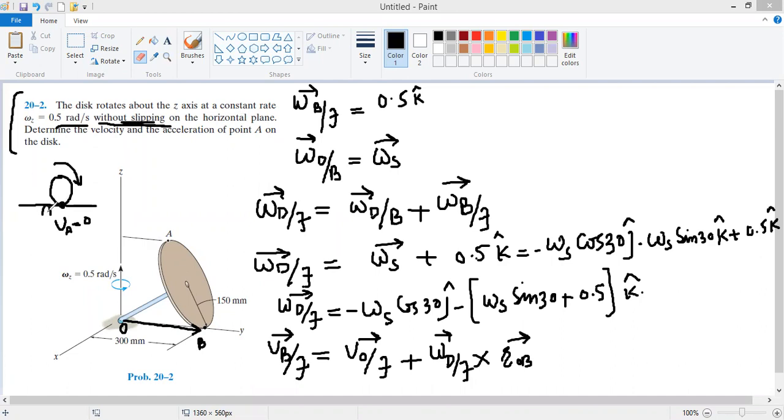If this is point A, its velocity comes to an instantaneous rest. We know this from rolling. The point of contact instantaneously comes to rest, though it has acceleration in the upward direction, as we have done in the kinematic analysis. It does have acceleration, but this is the point which instantaneously comes to rest, what we have been calling the instantaneous point of zero velocity. This point comes to rest.